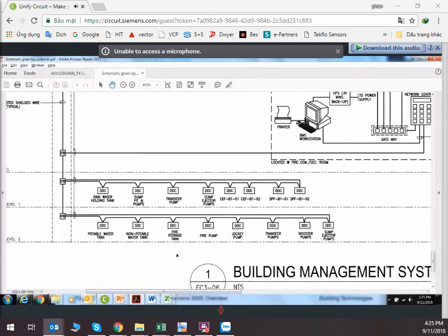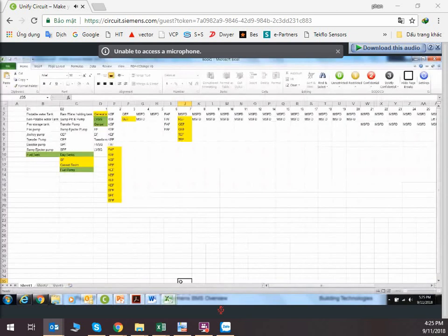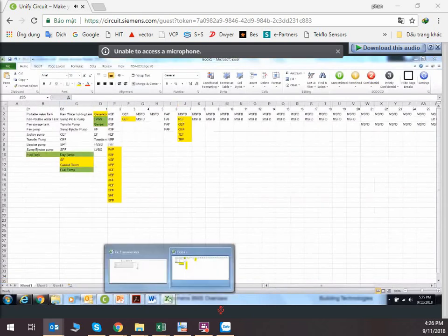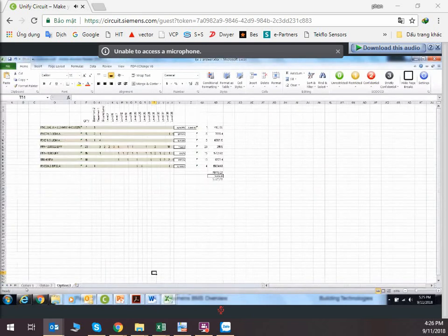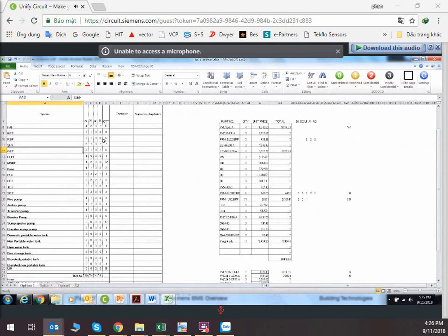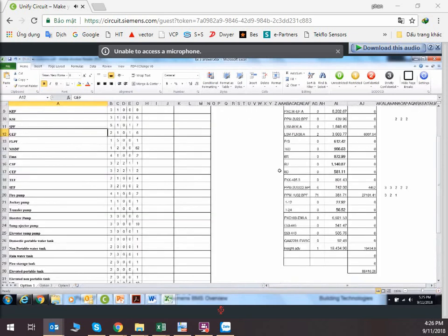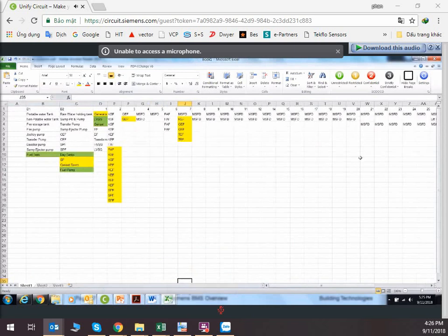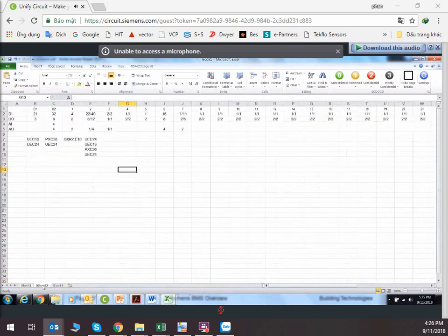So with this, at least you can consolidate the equipments. Okay. So of course, with this, the first step I will do is I will consolidate the equipments into their floor. Okay, different equipment in their floor, and then every equipment we are given the point count already. With all this, we can start to consolidate them into different DIDO, things like that. You can even separate them into left and right riser.